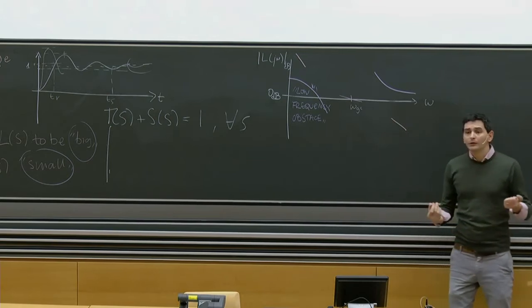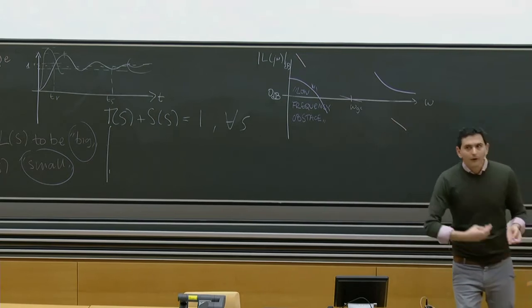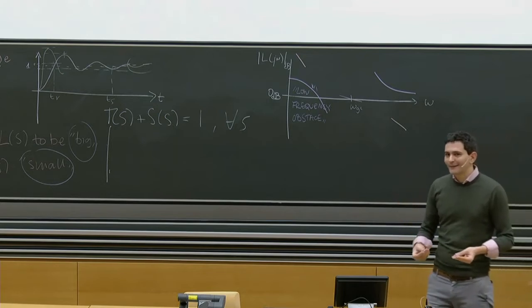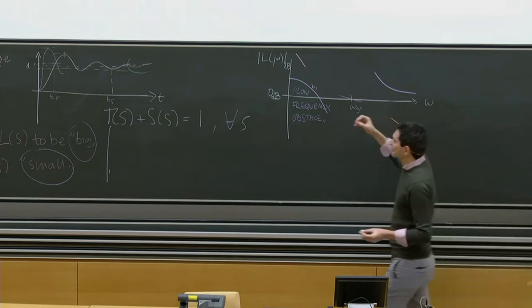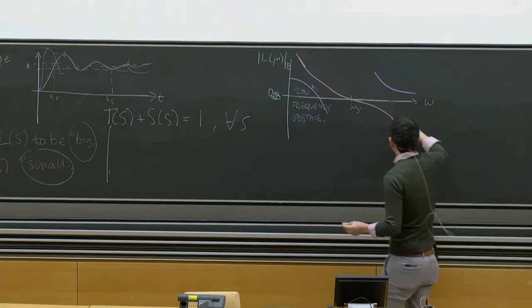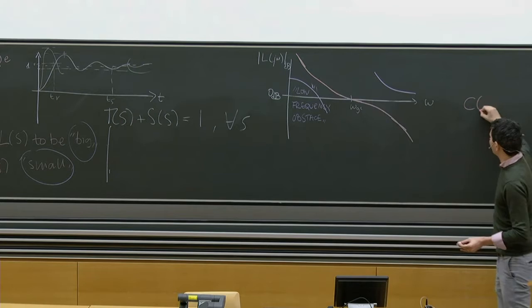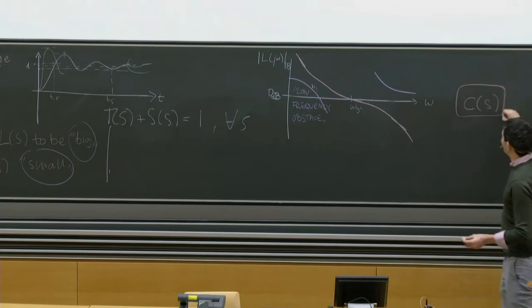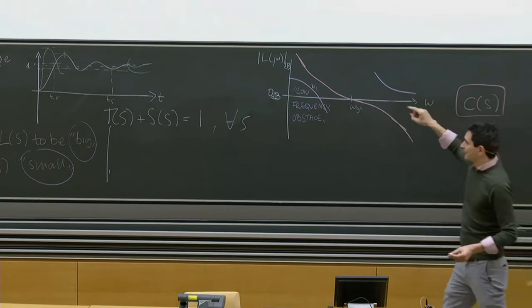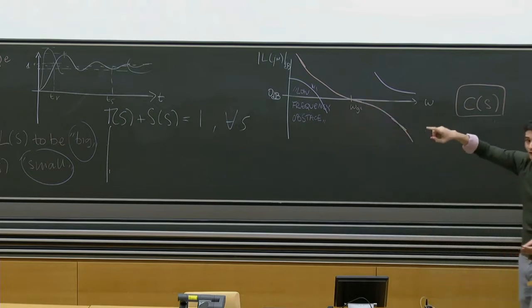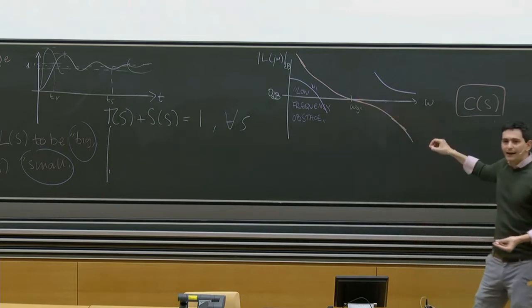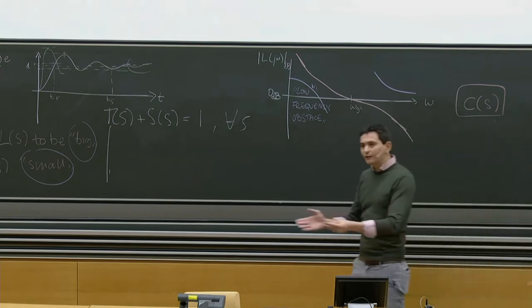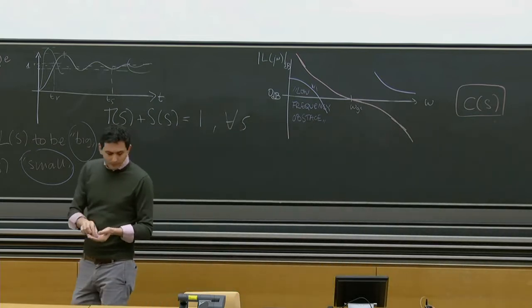Okay, so one way of seeing control systems, which is the classical way, and it's a very powerful method, is to just pretend that the design of a control system C(s) is all about getting the L(s) of the closed loop system, that is the series of C(s) and the plant we actually want to control, to have this kind of path, to steer around the objects, okay?